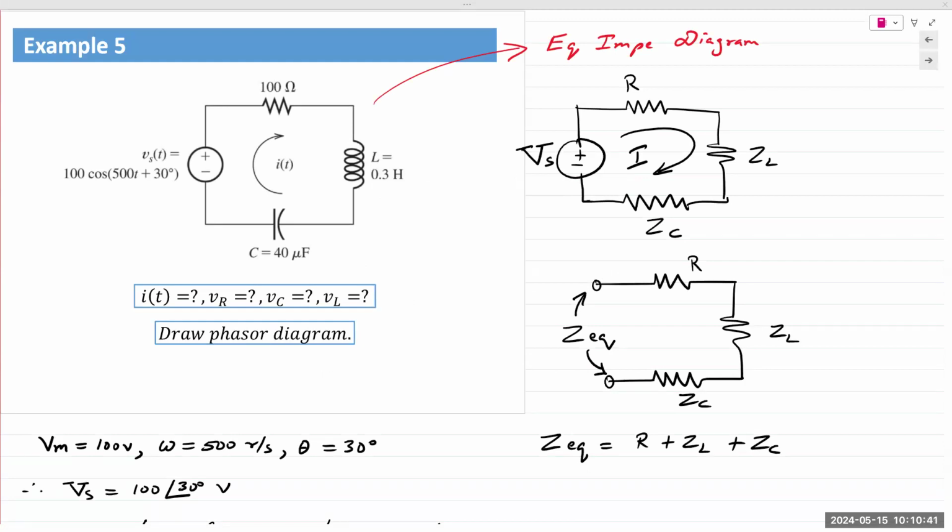All right. So in examples 1 and 2, we looked at adding or summing up two voltage sources or two signals, right? The same technique can be applied if it's a current source. If you have two or more current sources, you can combine them together by converting them into phasors. And then in examples 3 and 4, we looked at components, inductors and capacitors. Both examples refer to finding the current because you are given the voltage, you're given the impedance, and then you found the current. Now we combine everything together into one large circuit.